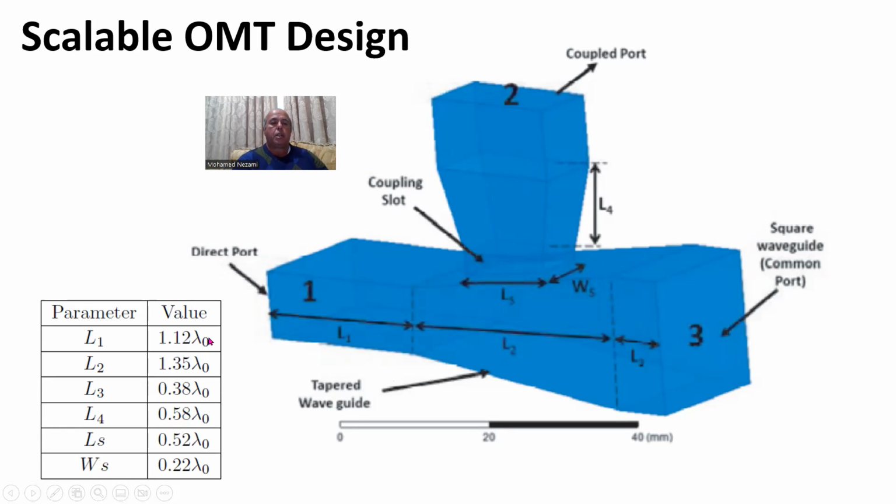So you design them basically as fractions of the wavelength. And once you fabricate this, by the way, the fabrication, I didn't talk about this, but usually this is symmetrical on one axis. So usually it gets designed from a brick of aluminum. You get a brick of aluminum and you split this in half, and there's two halves. So your CNC machine comes in, carves one side and duplicates it, and then you sandwich it together and screw it tightly together, and of course, very tight tolerances.